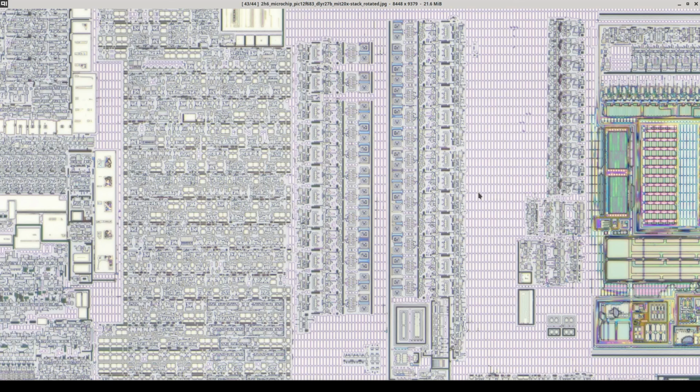One is that there's an undocumented chicken bit for some additional feature that is not mentioned in the datasheet that's just permanently fused off. The other possibility is that it's entirely vestigial. One of these fuses may not be connected to anything at all, and it may just have been left over from an earlier version of the design and it was too late to change.